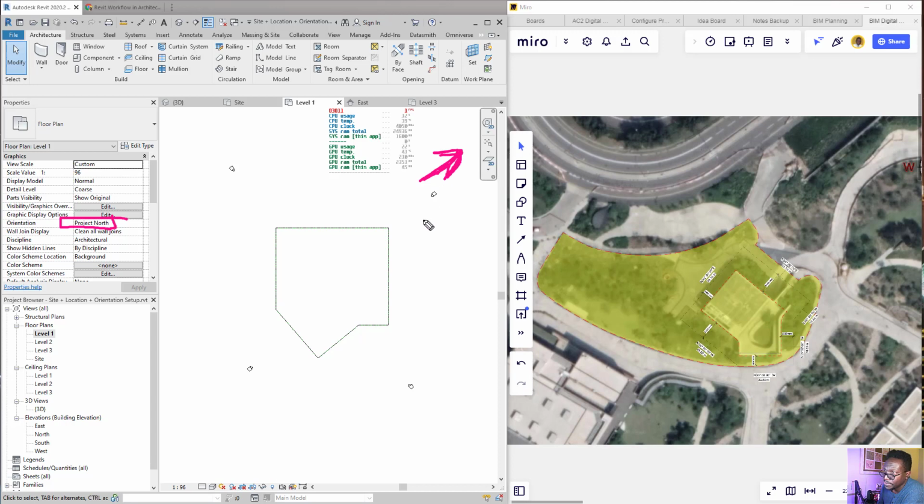All right, so that's our north. And remember, Revit was originally aligned to that north. For example, these icons here represent our elevations. We have an elevation view like that, an elevation view like that, and so forth. Now, this might not be ideal, as we'll be looking at the building at an angle, but it's definitely ideal to orient the building like this, because it's easier to draw walls and windows and all of that, which is why we had a Project North.